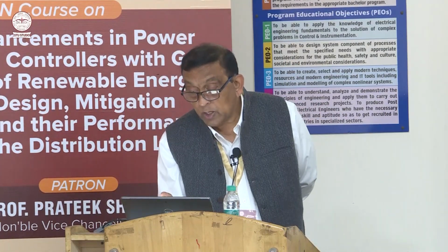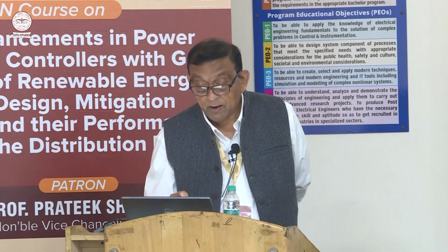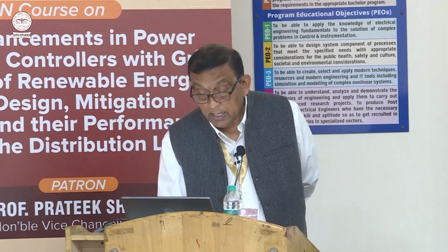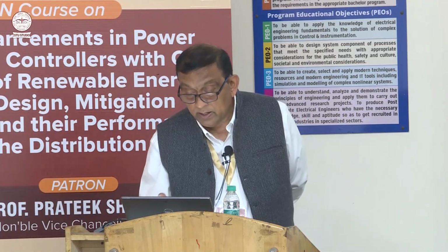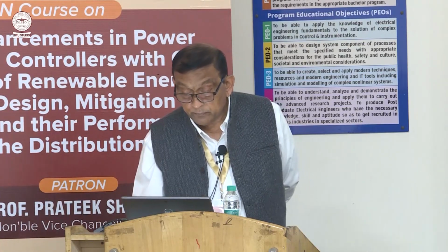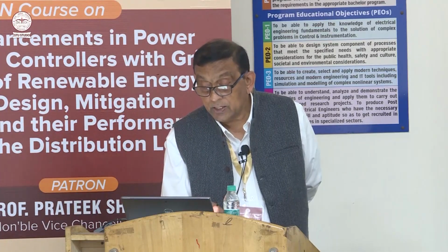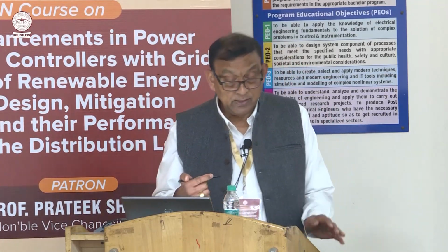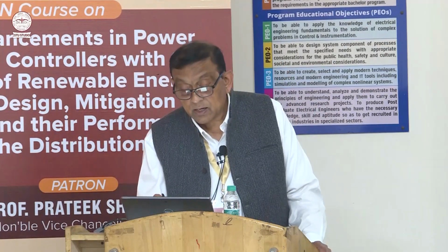Now it is a mature technology for providing harmonic current and reactive power compensation, load balancing, and neutral current compensation. Shunt active power filters are also used to regulate terminal voltage, to suppress voltage flicker, and to improve voltage balance in three-phase systems. So there are so many applications, and so much development has taken place in this technology with varying configurations and advanced control studies.